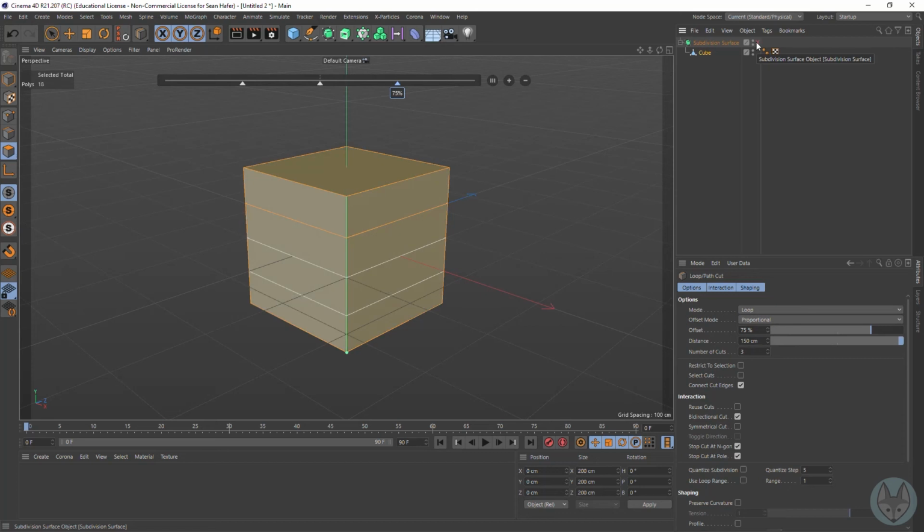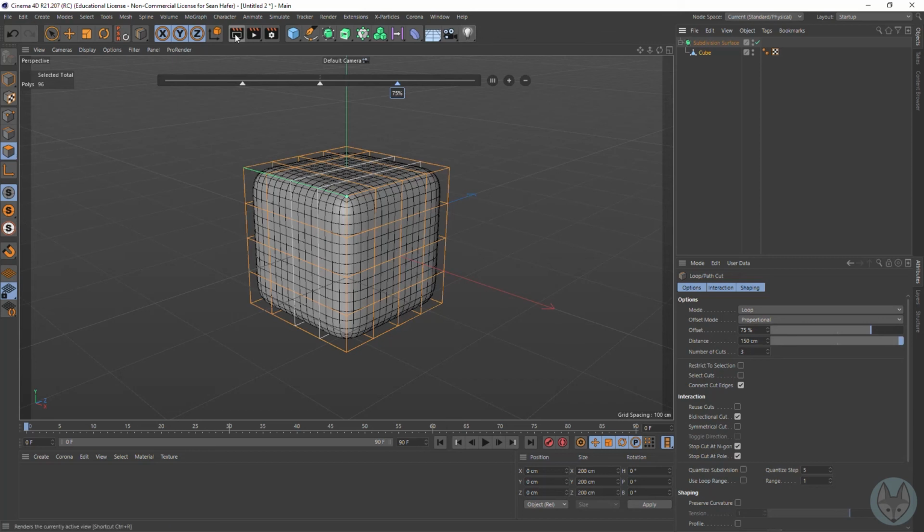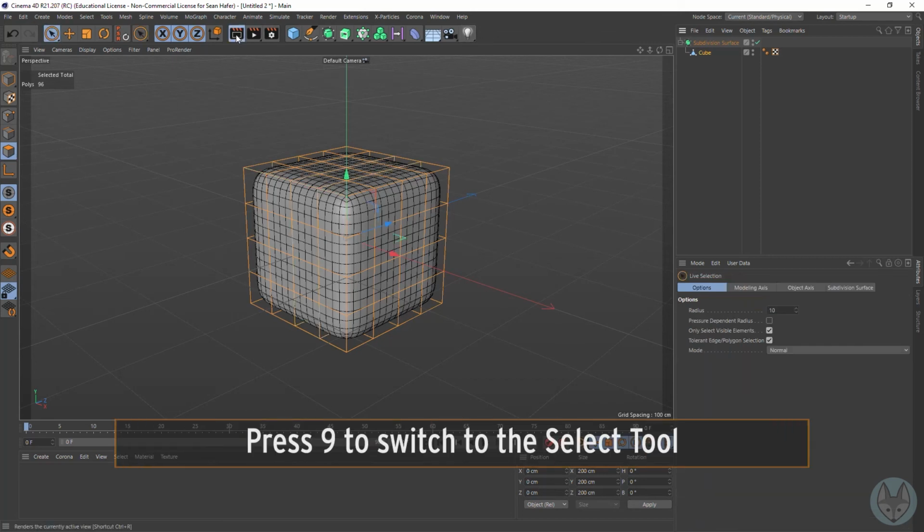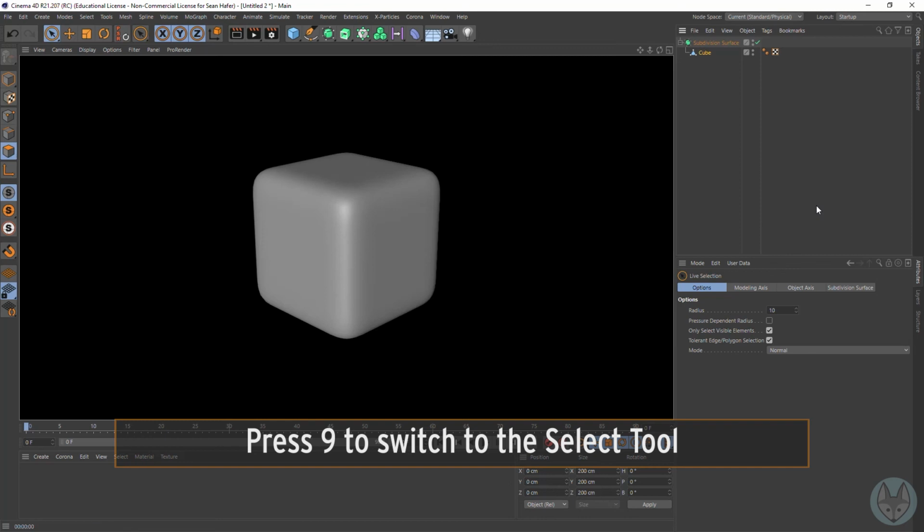All right. Now, if we want to do the same thing on another plane, we could come in here, cut again. Again, I could say 50%, and then do a 1, 2, 1, 2, and then maybe I come over here, click 50%, and then maybe 1, 2. All right, so now if we turn that subdivision surface on, it looks just like a smoothed cube. Okay, so it's a little nicer.